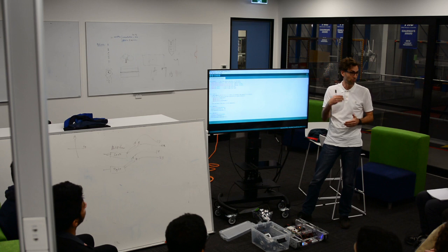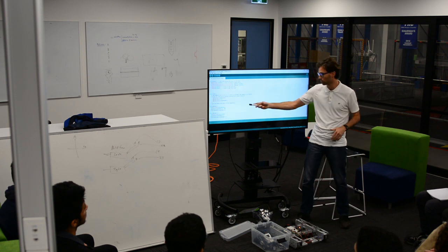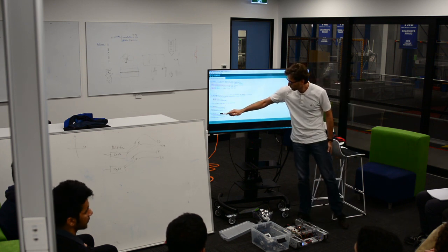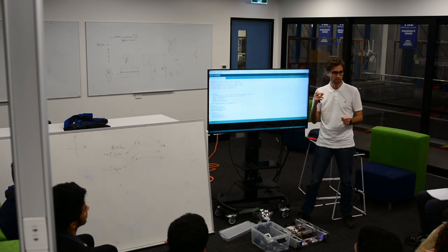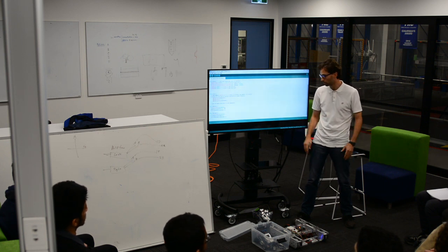And good control systems rely on rapid feedback. Get the state, change the state, get the state, stay in shape. And if that gets slowed down by doing other things, it's bad. So the interrupt service routines need to be short and snappy. No delays, no long-term communications, no potential waits, nothing.